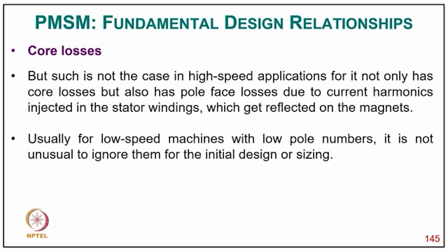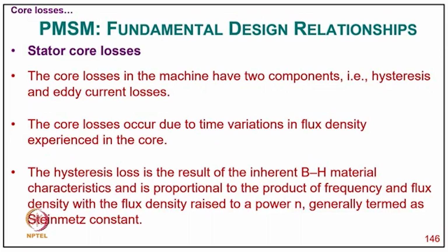But such is not the case in high-speed applications, for it not only has the core losses but also has the pole face losses due to the current harmonics injected into the stator winding, which get reflected on the magnet. Usually for low speed machines with low pole numbers, it is not unusual to ignore them for initial design or sizing.